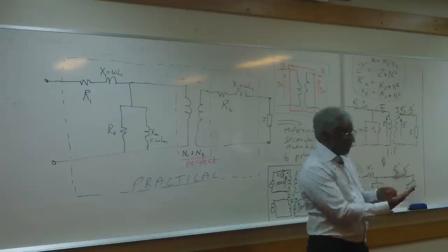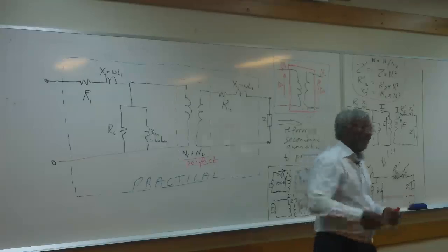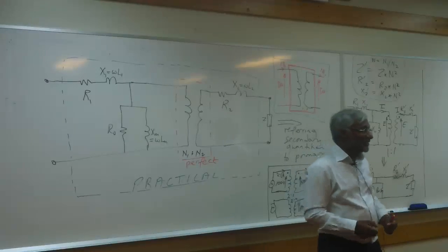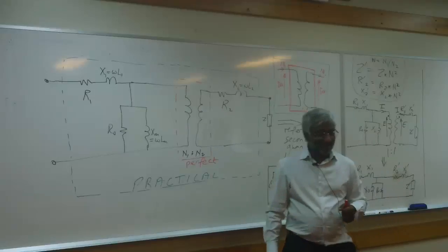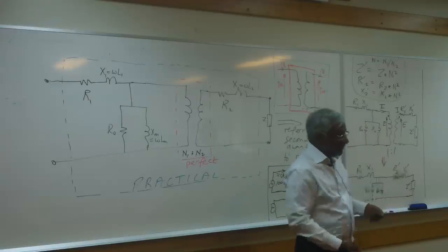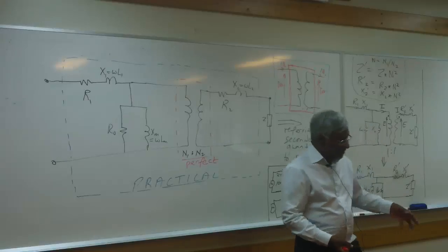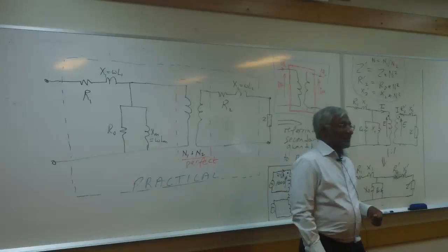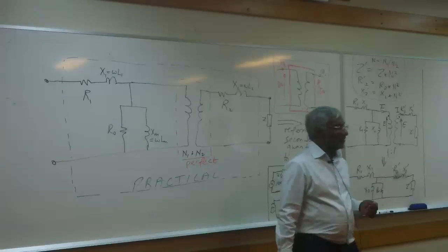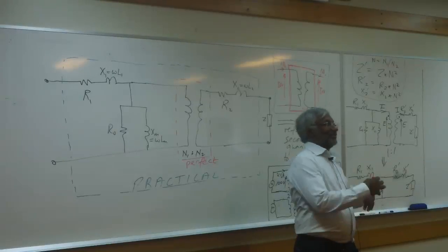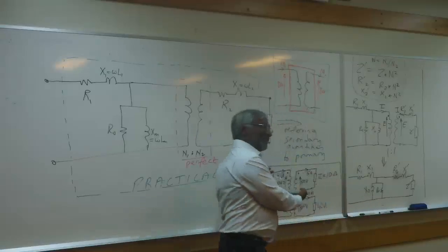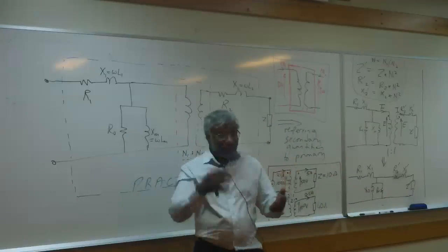They've got what they call a test plan. So they take their test plan, jump in their ute, drive to the substation, get their test gear, which is sometimes a variac. They connect it to their transformer, wind it up, measure some current and voltages, do some calculation, and get a value. But how do these things they are doing relate to the theory? And that's what I'm trying to do.